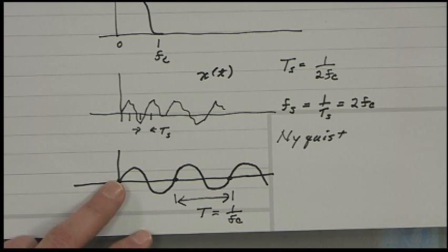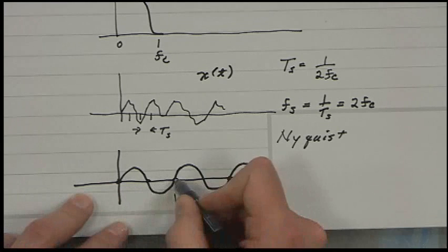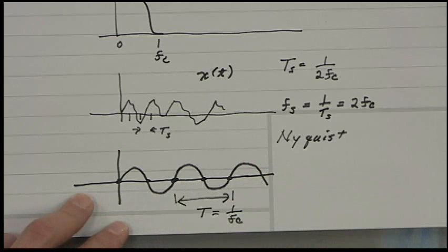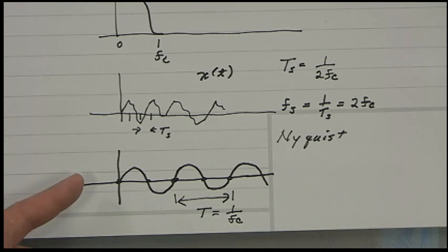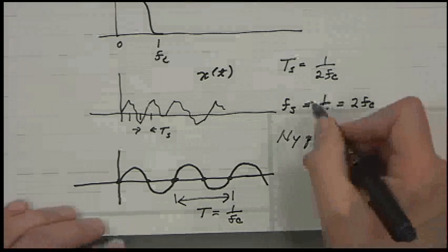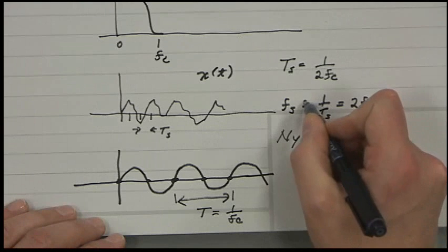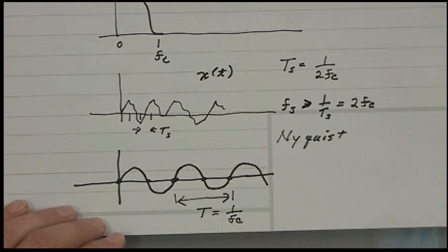If you sample at twice the highest frequency, they're still actually all at 0. Okay? So you actually have to sample just a little higher than that. And that theoretically allows you to reconstruct the signal. Okay? So if you sample at just the Nyquist rate, actually this isn't quite true. It's got to be greater than.